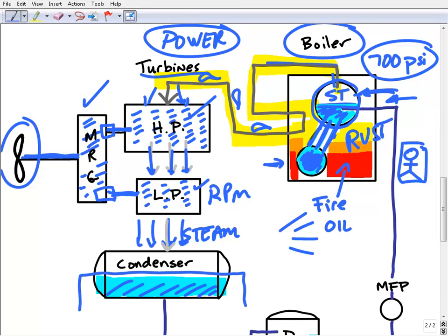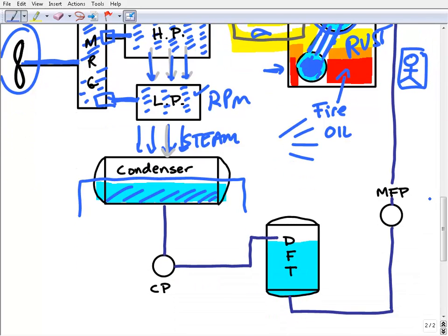So we have to be extremely cautious on having water that's treated to reduce rusting. And once again, this is an oversimplification, but I think it captures the gist from an engineering standpoint. So that's why we want to recapture this water. Remember, we're using chemicals, it's treated, so we don't want to just continue that on. That would be very expensive and really inefficient. So that's why we have the steam cycle.